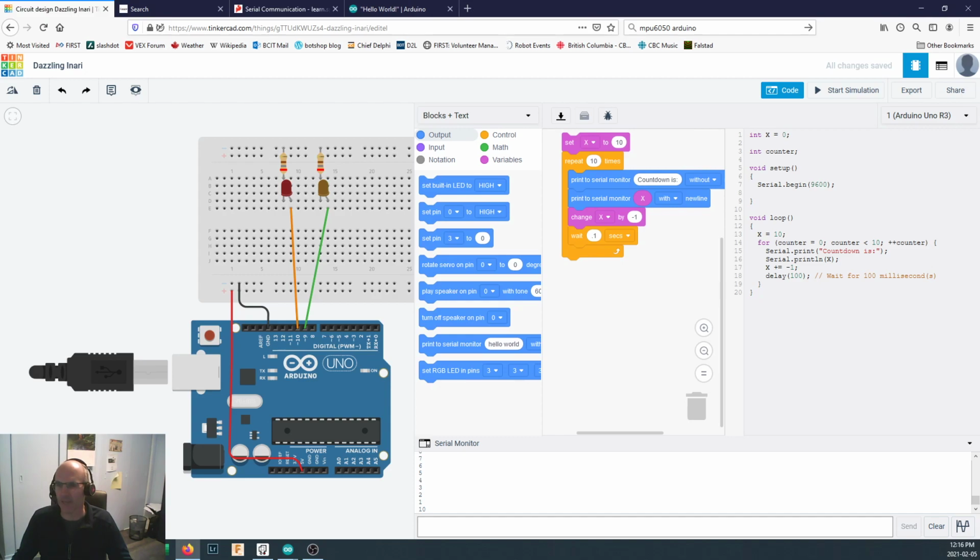The serial print statement is going to print the literal. Literal is for anything that's not a variable, okay? So it's going to print out these characters. It's going to send each one at a time. It's going to translate that into a stream of bits. It's going to pump it down that serial line, flashing the pin on and off in the right pattern to represent a capital C, then a small case O, U, N, T, all the way down here.